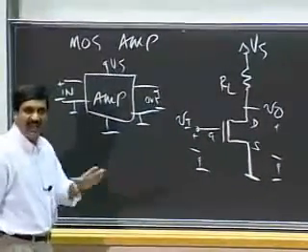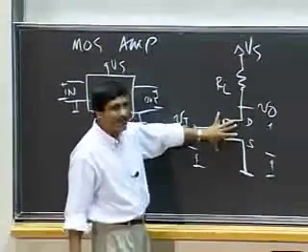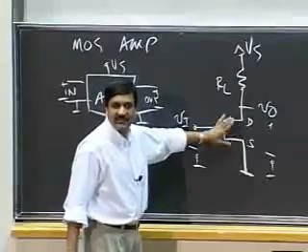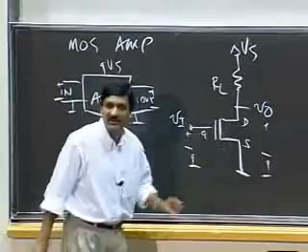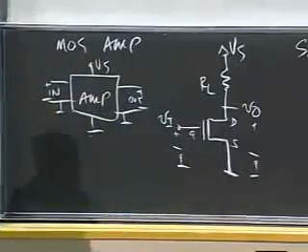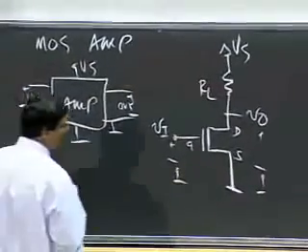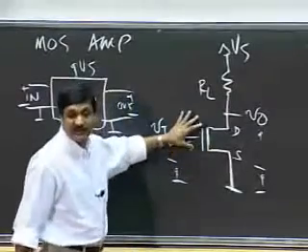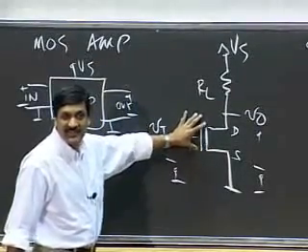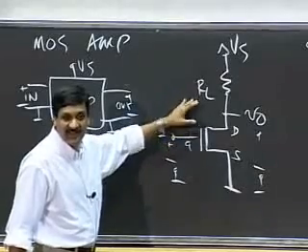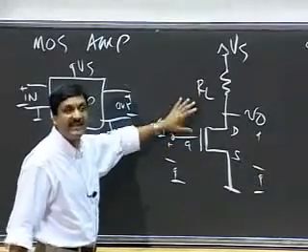What I haven't told you is that if this is operated in the linear region, it's much harder. In fact, you do not get amplification. I won't cover that, but you can check that out in your course notes as a discussion, or you can try it out for yourself. Replace this with the SR model for small VDS, and you can show yourselves that you don't get any amplification.